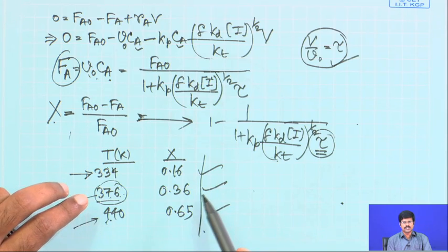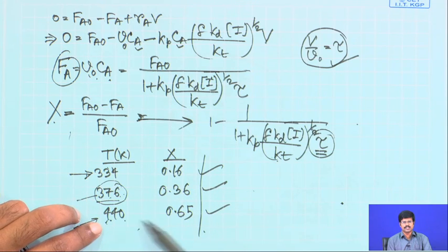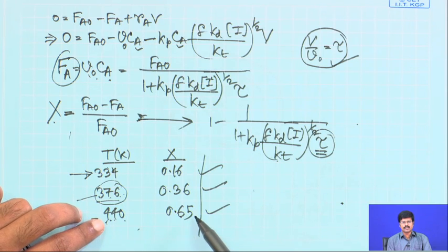So, you could also say that I would go to a very high temperature and then I can get very high conversion. So, one problem there is that oftentimes this temperature may be quite close to your ceiling temperature. So, that is a problem to do the reaction in, and also you are doing the reaction at a high temperature, and remember that it is an exothermic reaction. So, the safety is also an issue.